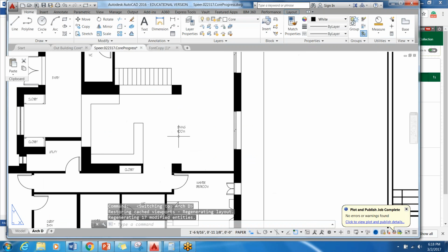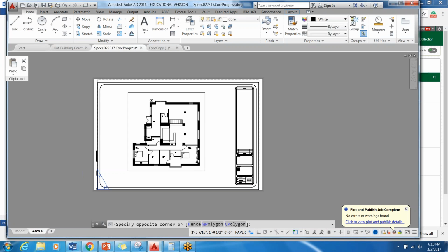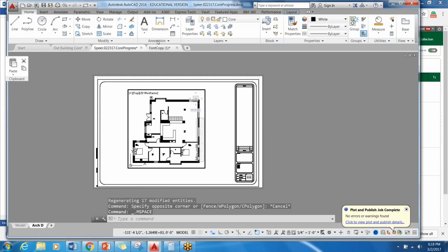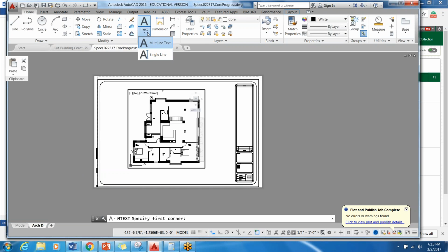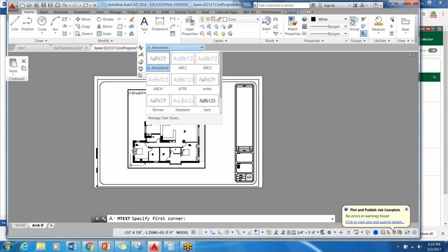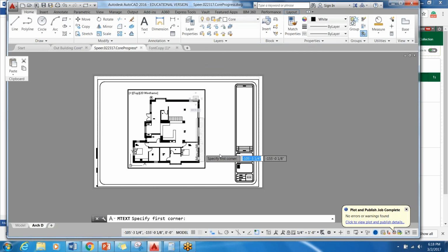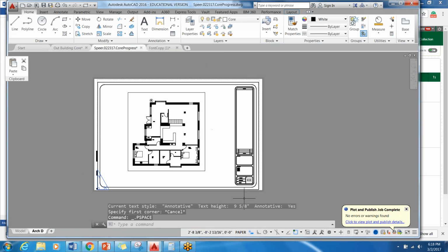Okay? So say she wanted it to be 6. She has to do it in here with annotative text by double-clicking into the layout, coming up to her normal multi-line text, making sure that it's truly annotative. That's been set up with City Blueprint as well. So this is where you use annotative with the City Blueprint setting. She clicks on that to make sure I see it. It looks like City Blueprint and annotative. Okay, I'm ready to just roll. She wants to make sure though, quick step, that it is locked so then she can zoom in and out without moving it. Lock.